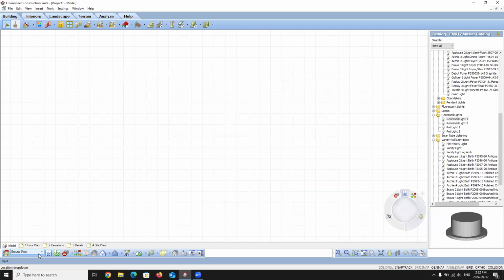The building location settings will dictate the number of building locations in your project, to a maximum of 999, and the name of each of those locations. The relationship of the different building locations to one another and to the ground. We're also able to dictate the wall, the floor, and the ceiling heights of each of the building locations. We can also control the height at which elements such as doors, windows, and openings are placed into our models. And then we're also given the ability to adjust the framing settings for load-bearing and non-load-bearing walls in our project.